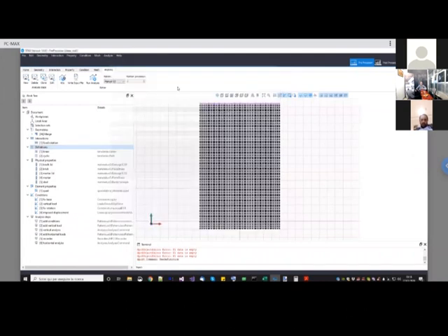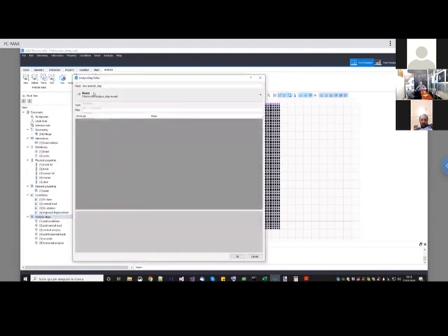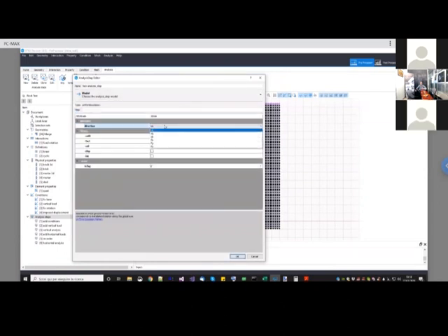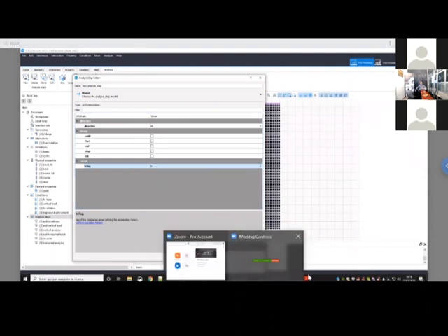So you have this extra time series, and now instead of creating this impulse displacement, you can create a uniform excitation in the analysis step, like this one. You go under pattern, add pattern, uniform excitation, and here you choose the direction, and you choose the time series for the acceleration. And basically you're done with nonlinear time history analysis. Okay, let me go back to the questions.